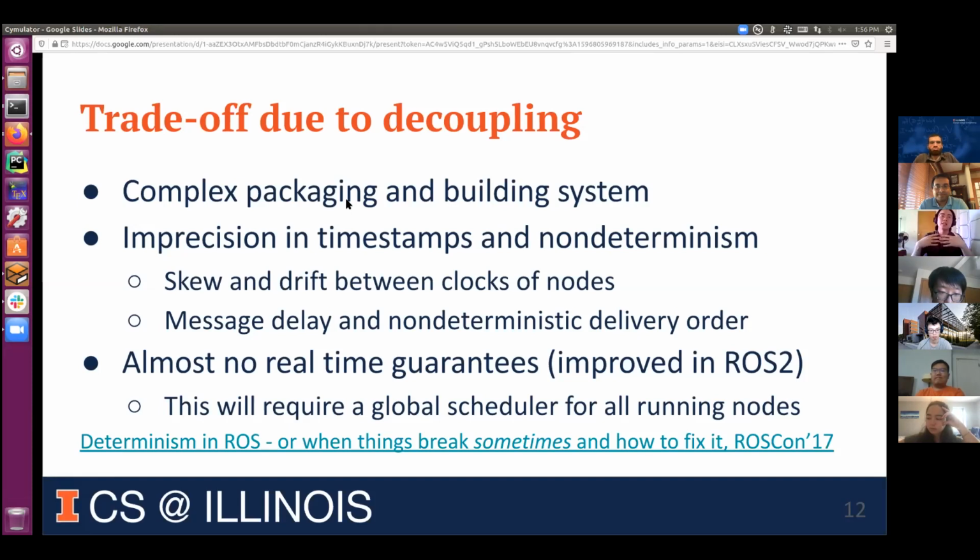And the other thing is that message passing actually introduces extra delays. So the timestamps on your, for example, sensor positions might be imprecise at first, or second, when it is delivered to where your controller is, it is probably long enough to violate something.